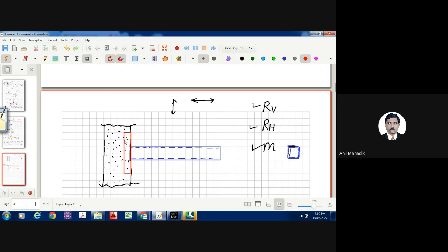Okay, so I will attach one steel plate, embed the steel plate into the column, right? ये समझो स्टील प्लेट है हमारा. अभी how to attach स्टील प्लेट को? यहाँ तो थोड़ा weld करेंगे, but welding will not be sufficient here in this case. Okay, यहाँ weld करेंगे, there is no problem. We can say I will put one bolt over here. यहाँ ऐसे बोल्ट लगाएंगे, right?